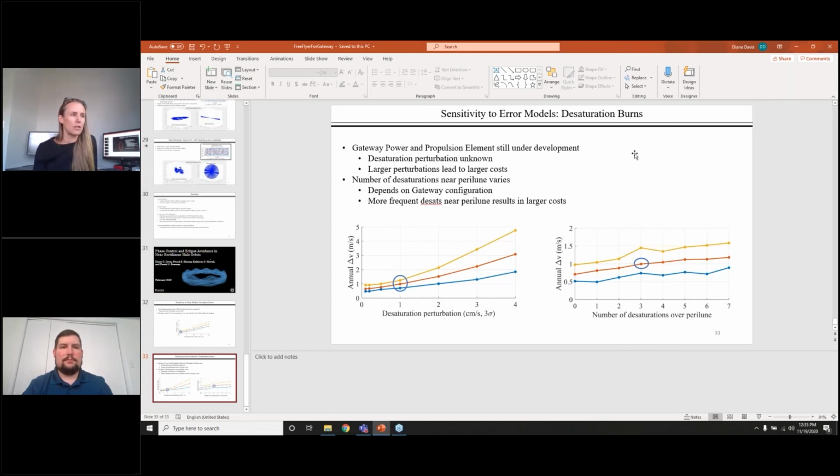What is more important is the solar torques. So what we do is we use FreeFlyer to compute an equilibrium attitude, a solar pressure equilibrium attitude, so that the solar torques don't add attitude control costs to our spacecraft. So that's really the bigger effect. The solar pressure itself isn't bothering us much. The solar torques can be bigger, and so we design an attitude to minimize those torques.